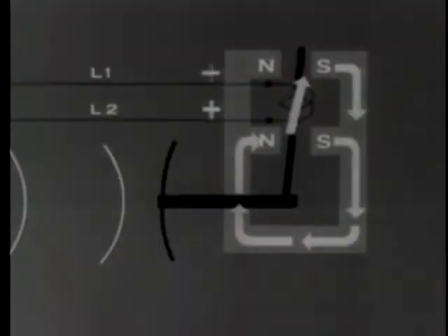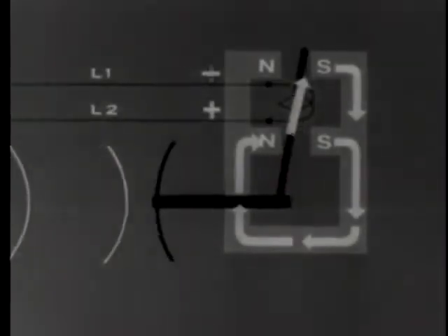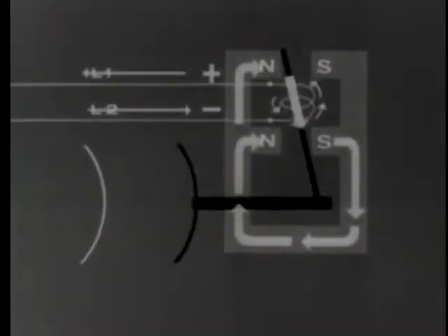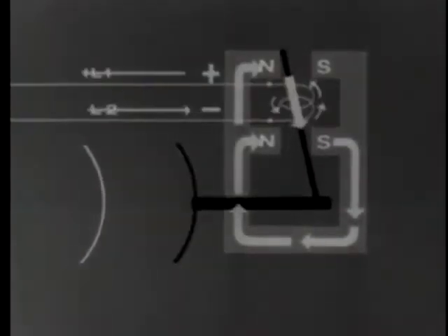By attaching a connecting rod from the armature to a diaphragm, similar to that found in a telephone transmitter, a direct linkage is effected. The energy of sound waves moves the diaphragm. Because of the direct linkage, any movement of the diaphragm is transferred to the armature. This means that an alternating potential will be induced in our coil, which exactly corresponds to the wave pattern of the sound waves. This is the way we transform sound waves into an alternating current capable of carrying speech several miles over a line.